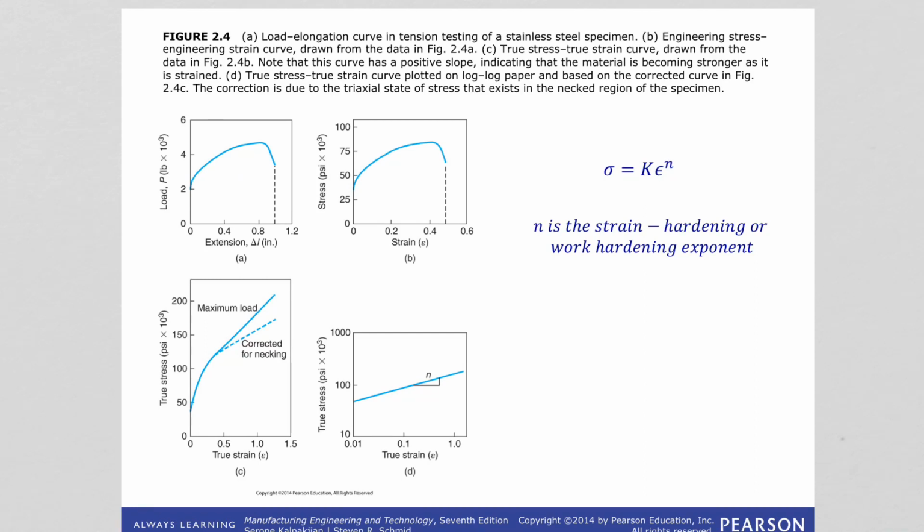So as I told you guys, what the device measures, always remember, is keeping the deformation rate constant. To do that, it is measuring the force that it needs to apply and also measuring the extension, the change in the length, and it is recording it like this. Then after this data is obtained, by the equations we learned, the stress equation and strain equation, by their definition, it is calculating the stress strain curve, and it is looking like this.